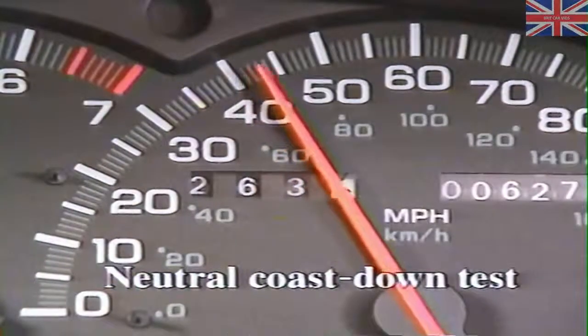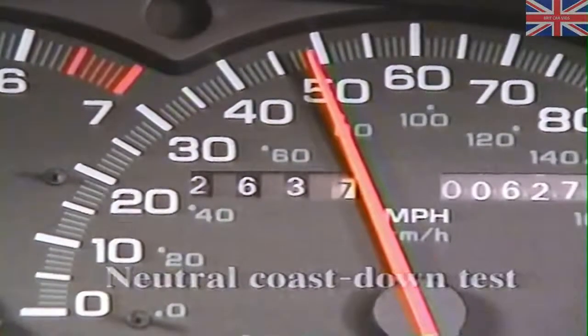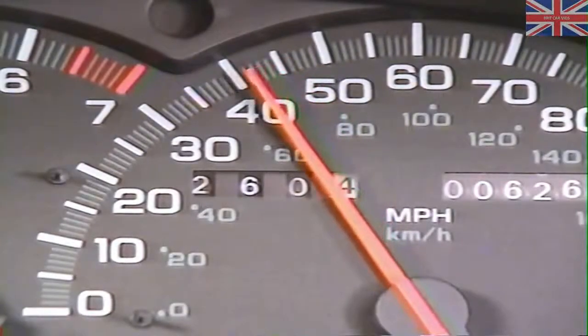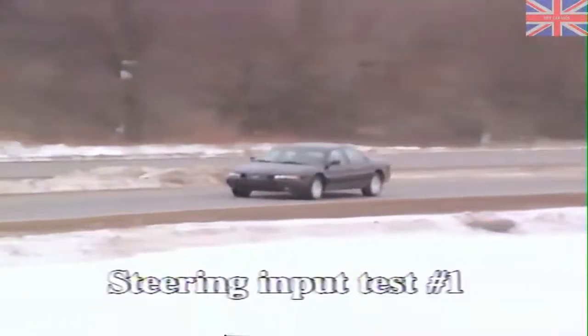The neutral coast down test should identify whether the trouble is engine speed or vehicle speed related. We'll accelerate to a speed slightly higher than the speed at which the problem occurs, then shift the vehicle into neutral and coast down through the vibration range. The vibration still occurs, so we can conclude that the vibration is related to vehicle speed and can therefore eliminate the engine and torque converter as the source of the trouble. Just to be safe, however, we'll perform the neutral run-up test after we return to the service bay to further confirm our results. We have one more test to perform while driving.